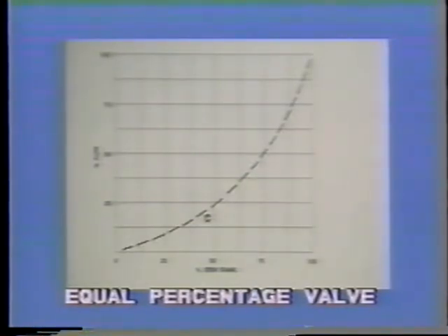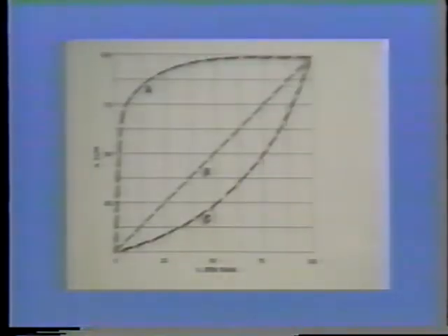The equal percentage valve, which is most commonly used, is very effective in controlling low flows by requiring a greater amount of stem travel for an increase in flow rate. This produces a better turn-down ratio for better flow control. Equal percentage and linear valves will generally meet the needs of most applications. Putting all three of these together on the same graph gives a better contrast between the different characteristics.